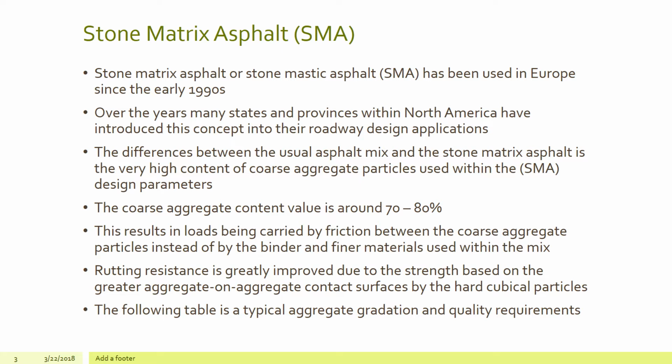Rutting resistance is greatly improved due to the strength based on the greater aggregate-on-aggregate contact surfaces by the hard cubical particles. And of course, the following table, which you'll see in the PowerPoint presentation, shows typical aggregate gradation and quality requirements for this type of SMA mix.